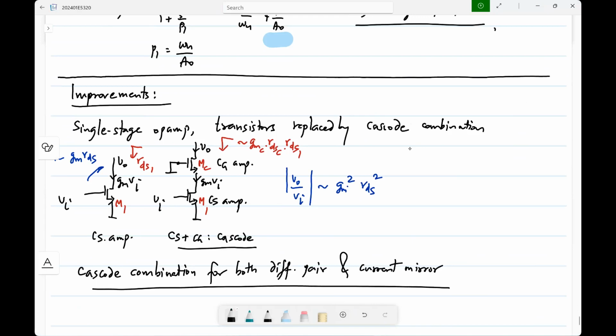Now, what would be the disadvantage of this? Any disadvantage that you see? Right. Earlier the output operating point had to be such that one transistor is in the saturation region, so the minimum voltage required is VDsat of one transistor. Now you have two transistors. The VDS could be smaller and maybe this will be better, but you can see there is some compromise in the swing limit.